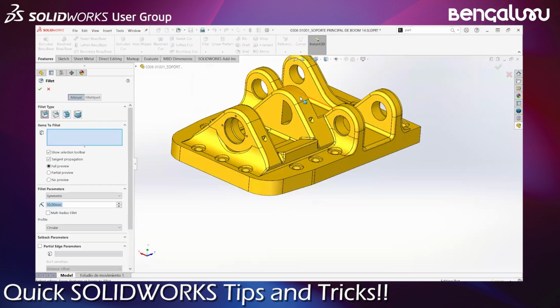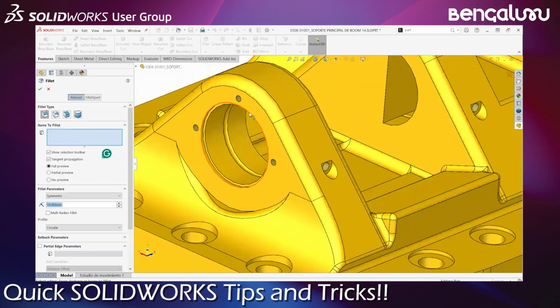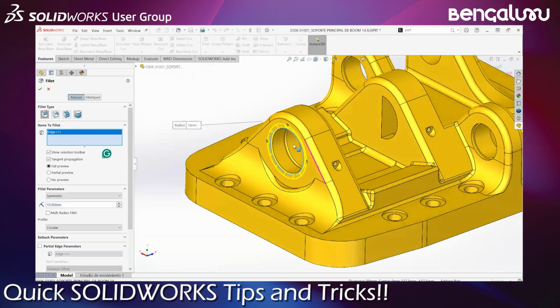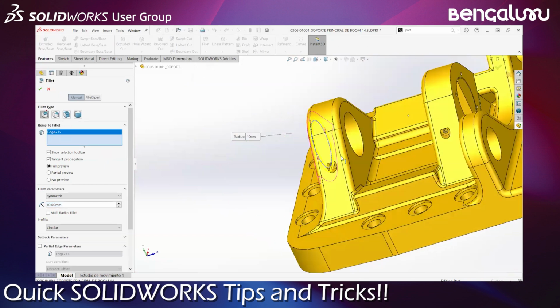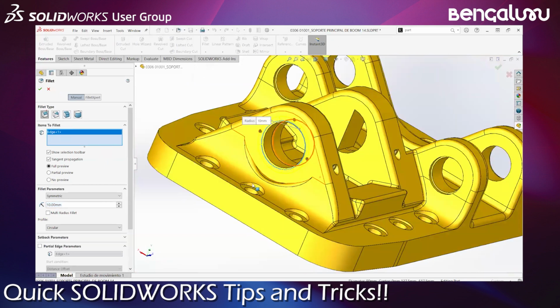Okay. So whenever you use a fillet command in SolidWorks, generally what we do is, if I want to add a fillet to this edge, I select this edge. And then if I want to add a fillet to the other circle, we tend to either select it from here if we can, or we rotate the entire model and select it from here. That's how we do it, right?